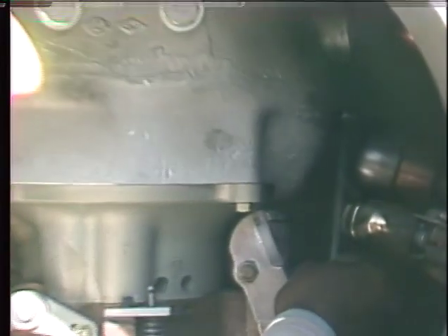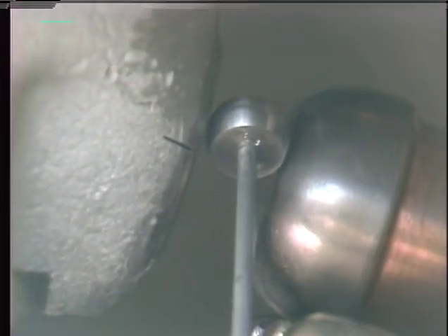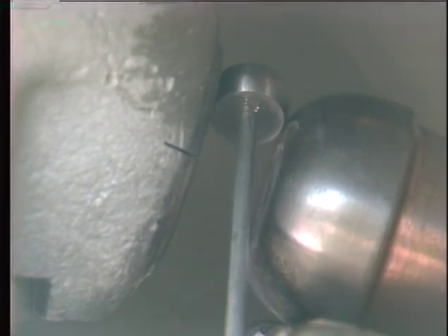For this type of breaker, the space between each arcing ring and arcing probe is checked. Here, a go-no-go gauge is used. The space between the ring and the probe should be such that one end of the gauge just barely fits between them, while the other end of the gauge should be just a little too large to fit between them.